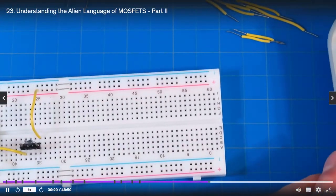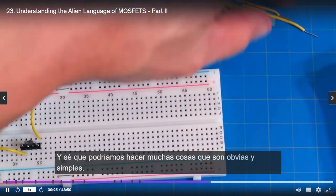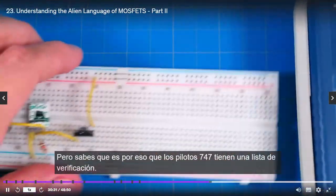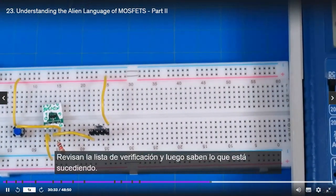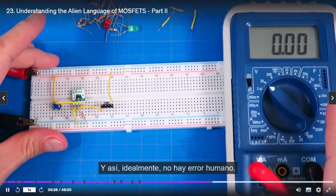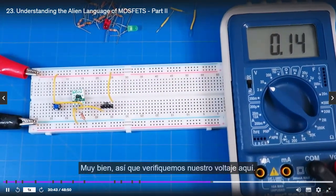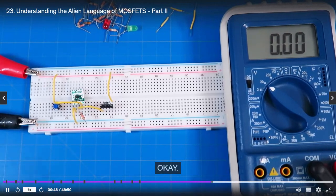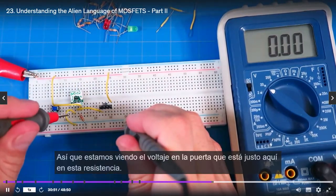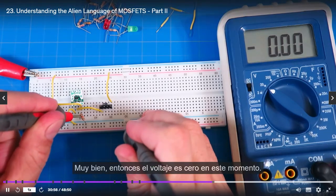Let's get out a meter. I know we're going to do a lot of things that are obvious and simple, but that's why 747 pilots have a checklist. They go through the checklist and then they know what is going on, so ideally there's no human error. Let's put this into voltage mode and check the voltage on the gate, right here at this resistor. Sure enough, the voltage is 0.